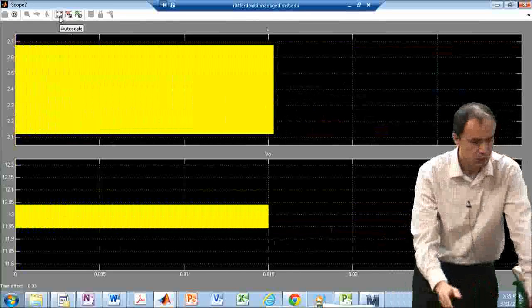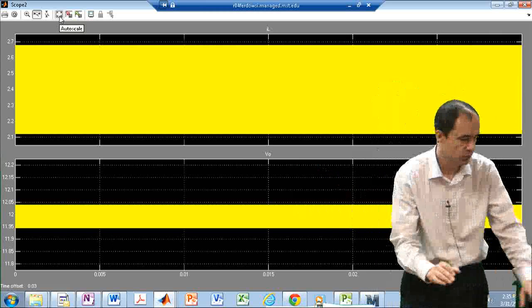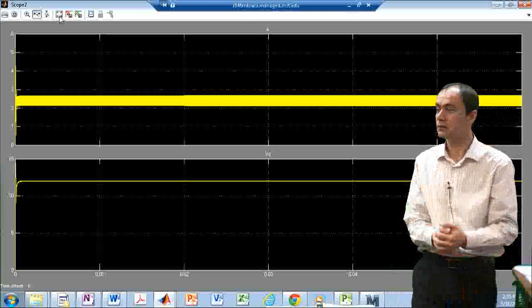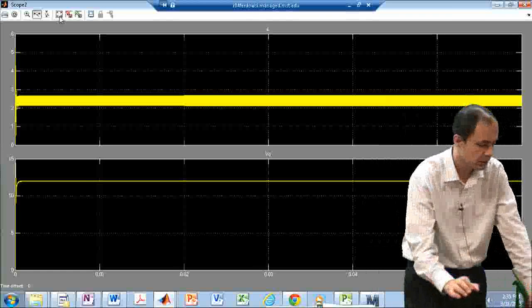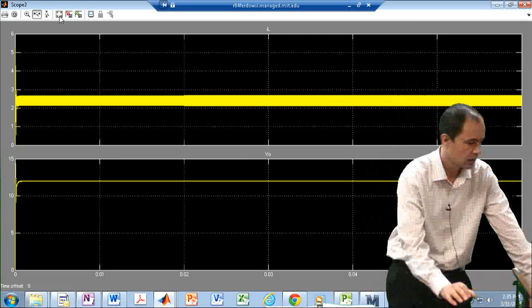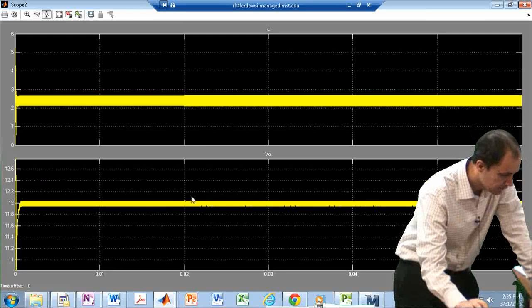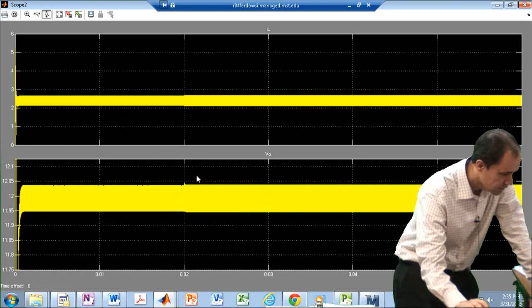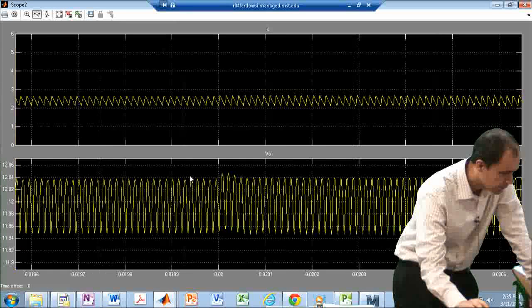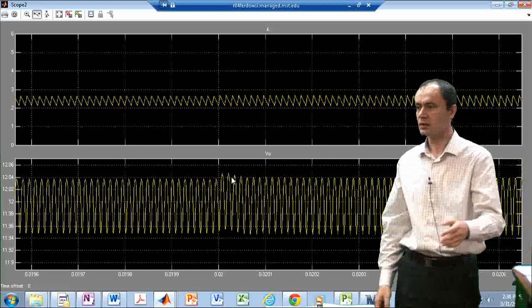Well, obviously, we are looking at our output voltage. Ideally, the output voltage shouldn't see these changes. It doesn't matter what the input voltage is. The output voltage should be 12, and as you can see, it is 12. So it's very good. It's doing a very good job attenuating or eliminating the changes in the input voltage. Although if you zoom in, you can see a slight difference over here, a very tiny little hump. It is almost insignificant compared to the switching ripples.